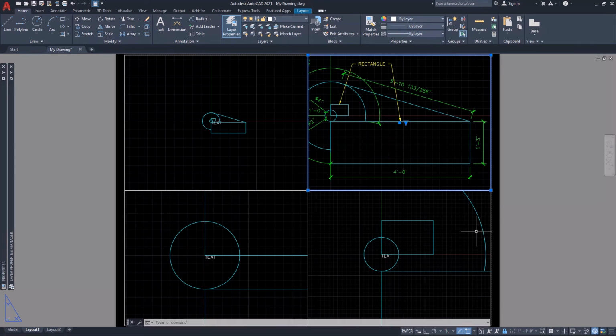Select both of the top viewport frames. Double-check and make sure that you are in orthographic mode by glancing down at the orthographic mode icon in the Drawing Aids toolbar. If orthographic mode is not currently active, the icon is not blue. Either left-click on the orthographic icon in the Drawing Aids toolbar or press the F8 key to make orthographic mode active.